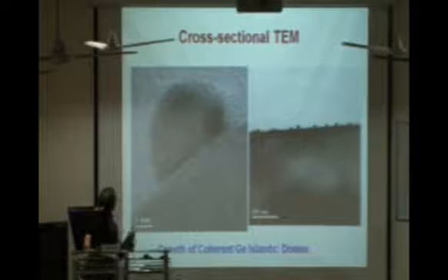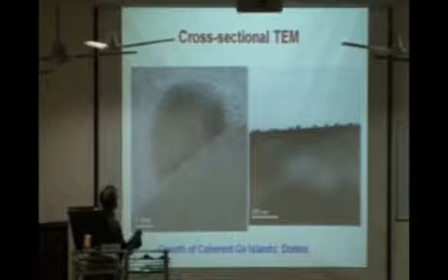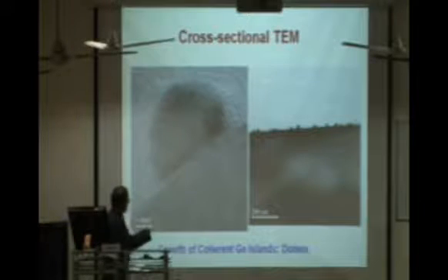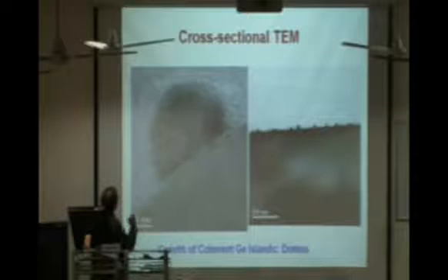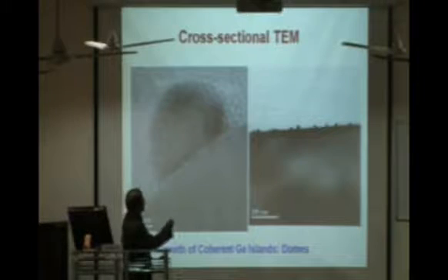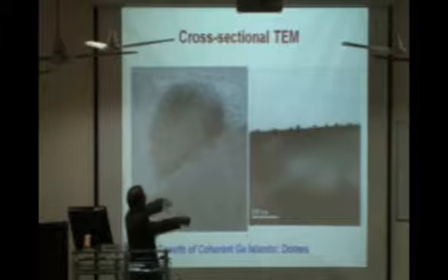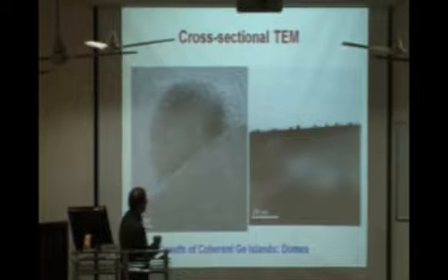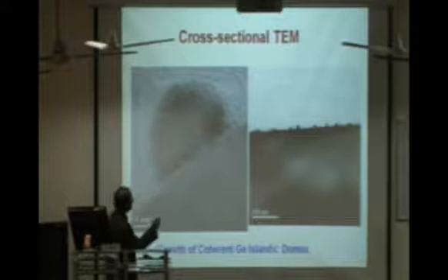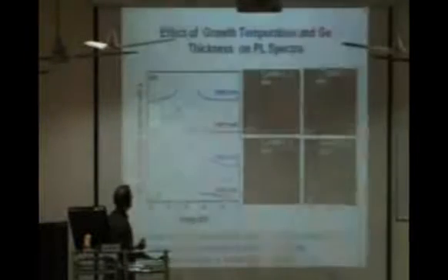If you image a single germanium quantum dot, it looks like this. This is the silicon substrate, and there is a very thin layer we call the wetting layer, where the growth is in 2 dimensions. Then it suddenly transfers to 3 dimensions. As you see, there are very nice interference fringes, which basically shows that this material is crystalline. And this shows a large number of quantum dots aligned on a silicon substrate. So now if you want to make devices, either you can make a single dot device or a multiple dot device.